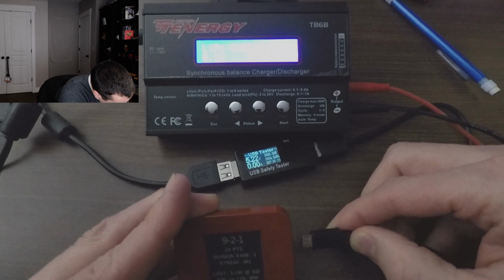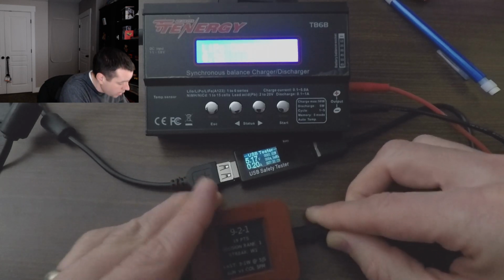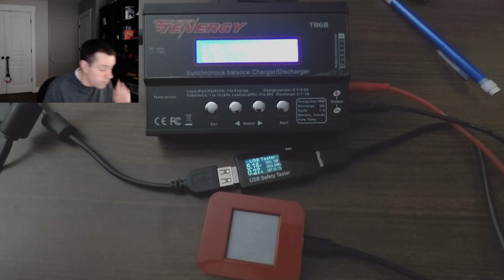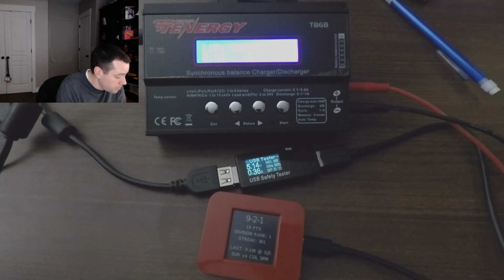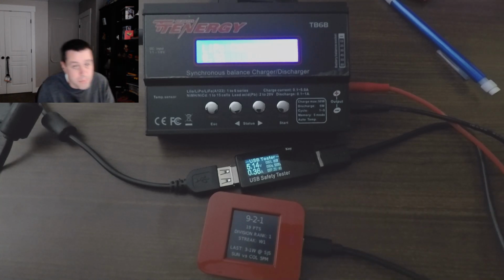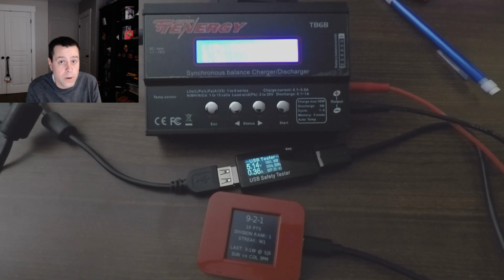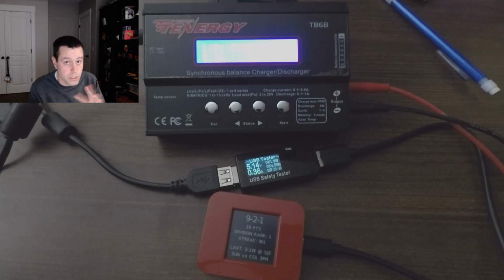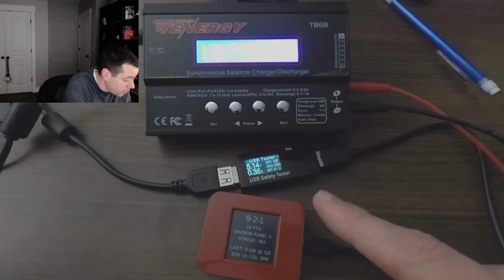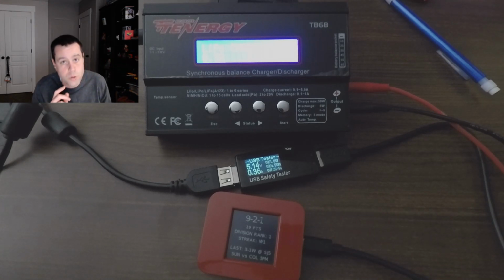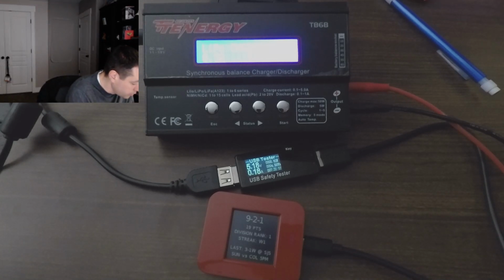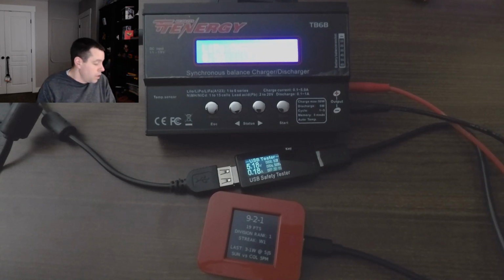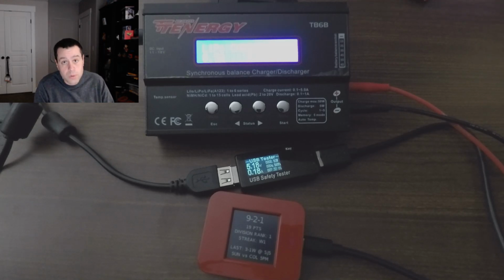So now we're going to connect it. And you see now we're up to 360, because remember we were at 180 before. It's going to update, we're still at 360, and that makes sense. 180 milliamps is going into the battery, just as we would expect, and 180 milliamps is going into keeping the Wi-Fi on. It's checking a bunch of things, and then it'll go to sleep here in a minute, and that should drop back down to 180 milliamps. So let's watch it right there. Perfect. You see that? Let me point with my pointer here. 180 milliamps. So perfect. That's exactly what I would expect.